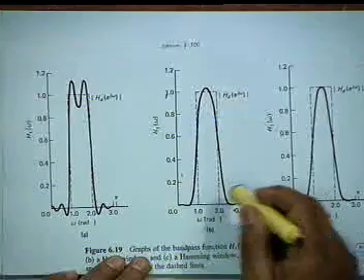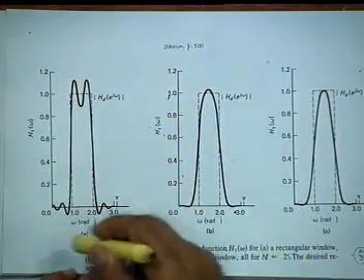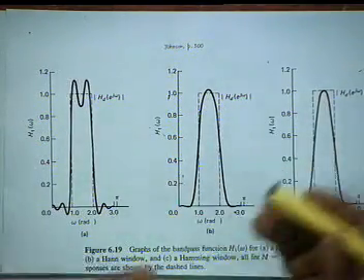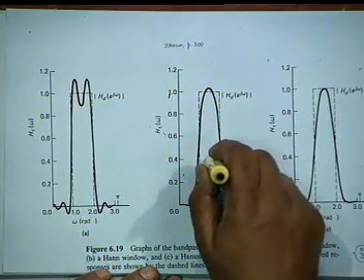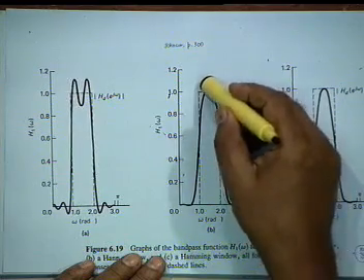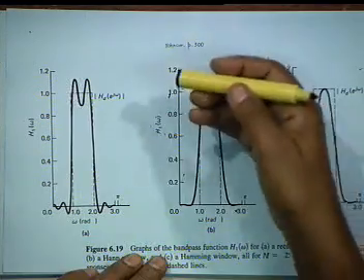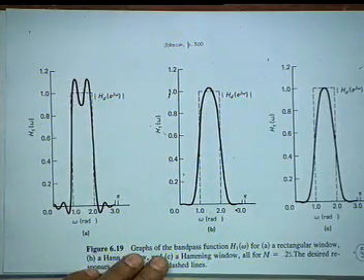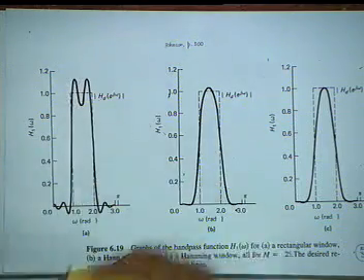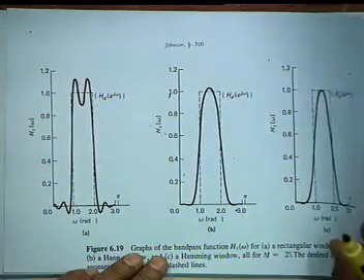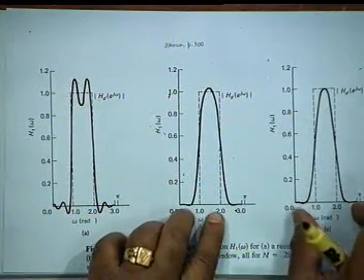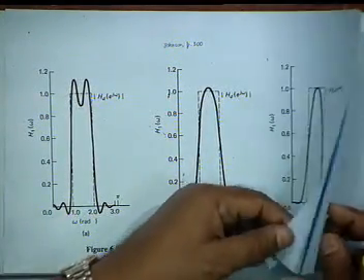There is a theoretical reason which you can find out, but there is no control for the Hann. Hann also goes towards 1, but you see this is 2 length less, and therefore there is still a slight deviation, but this is not important because you are going to divide by that amplitude. The rectangular is of course horrible, as you can see. Once again you can observe that the sharpest cutoff is here, then the cutoff slope decreases on both sides.